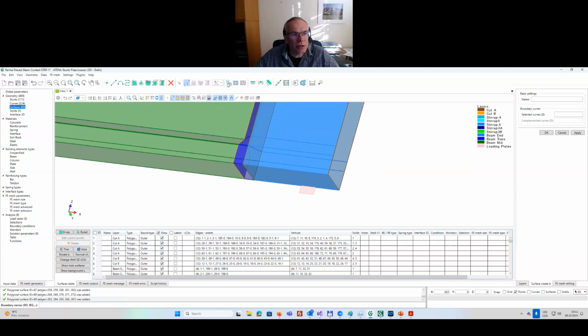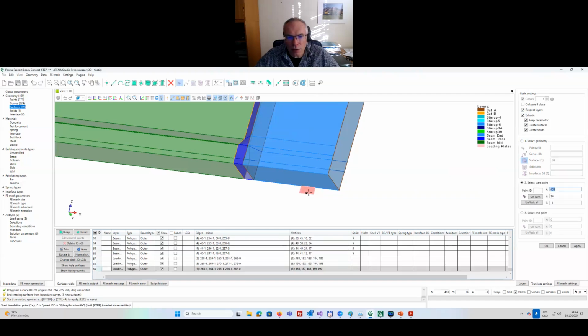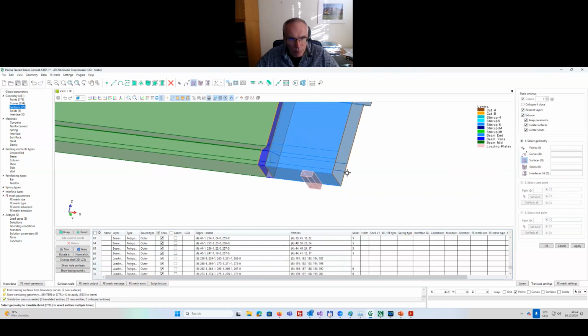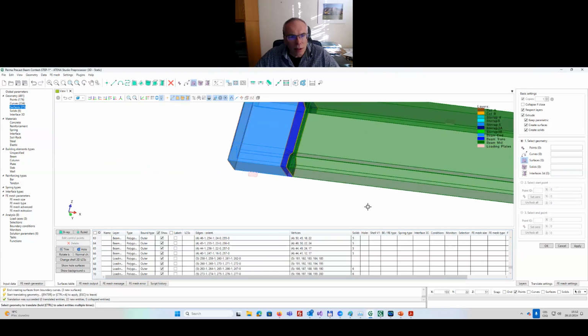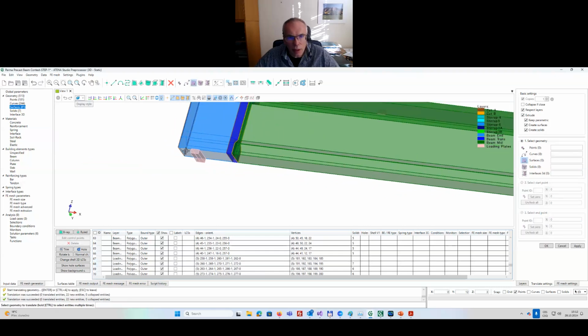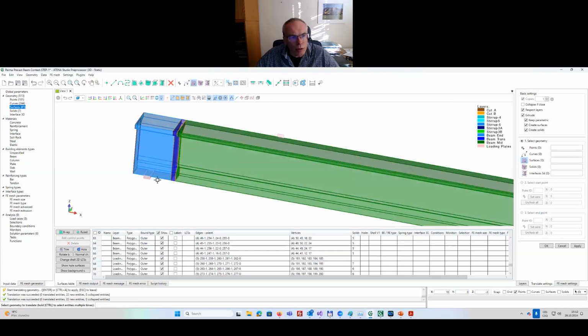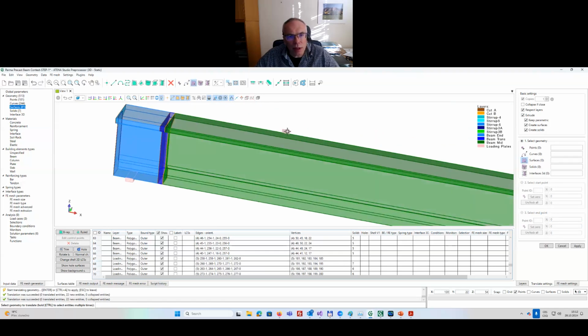extrude these surfaces using this extrude command, surfaces. So I click surface. Now I click define the extrude vector. When it is completed, one is already ready. So now I create the other loading plate on the other side and also the top one. Actually, those were at the bottom. I have supporting plates, and this one is a plate to apply the loads.